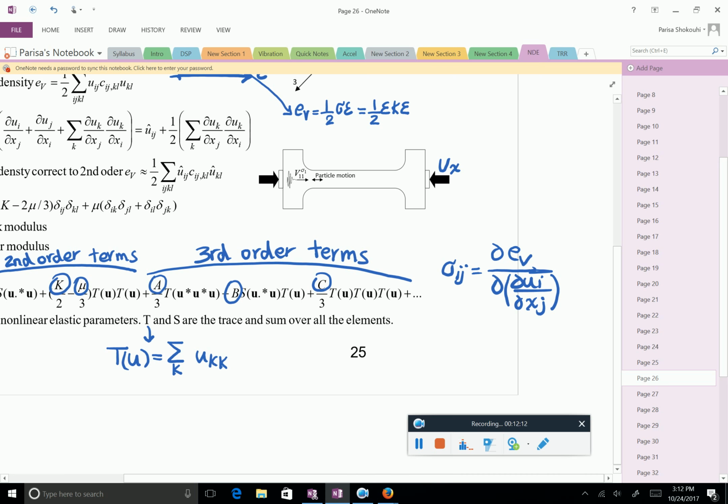And the other thing that you know, maybe you have forgotten, is the wave equation. The way that I will use it here is this expression: rho u double dot, in one direction, is just the derivative of sigma over x. If you look at the way we derive the equation in the one-dimensional case, this is the wave equation.